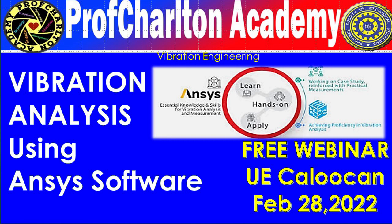Okay, so the amplitude will be higher, and the noise will also be higher, right? So people will try to avoid these scenarios. What they will do is make sure that the natural frequency is not overlapping with the operating frequency of the machineries. This will make sure there are no high amplitude vibrations in the system. So this is one scenario.